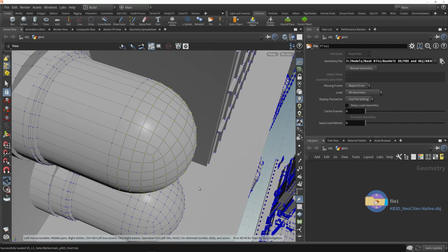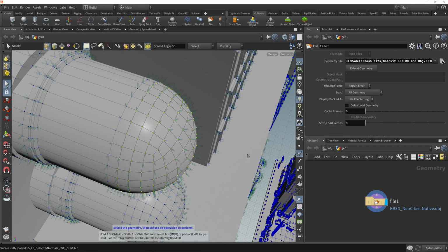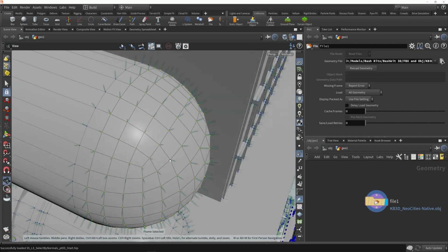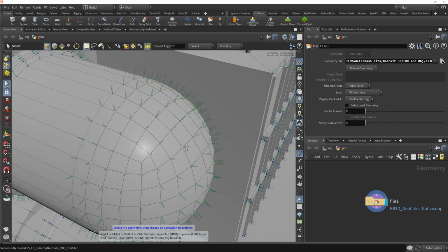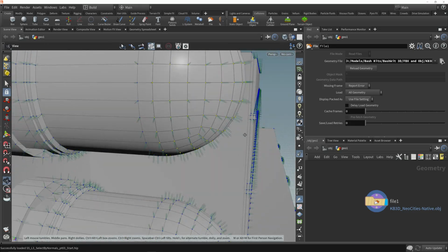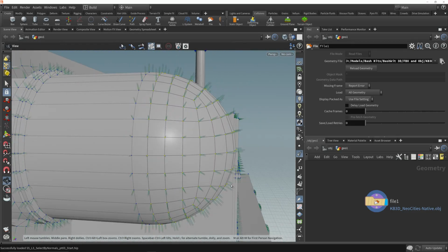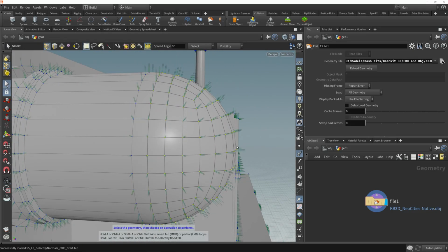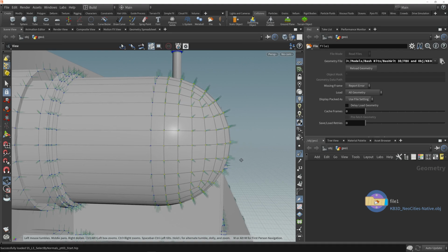This will be a bit easier to see if I turn on the vertex normal markers. And we can see that on this domed part of the mesh, the vertex normals are all pointing in the same direction as the point normal. And these normal markers just help us visualize the angle between the normal of the point which I clicked on at the very apex of the dome and each of the other points on the cap. And we can see how the normal of each of these points is within 85 degrees of the point which I clicked on.